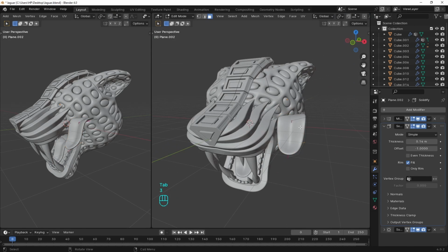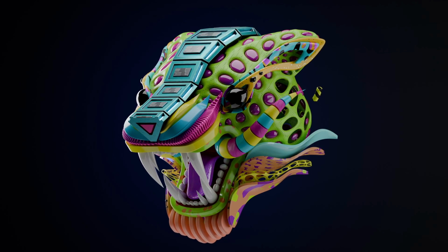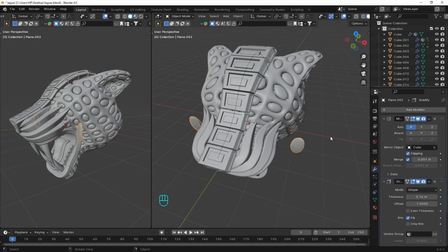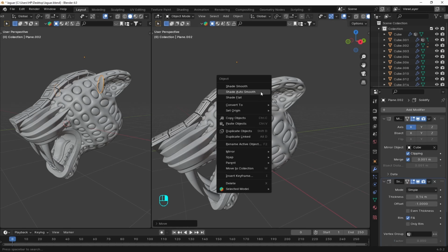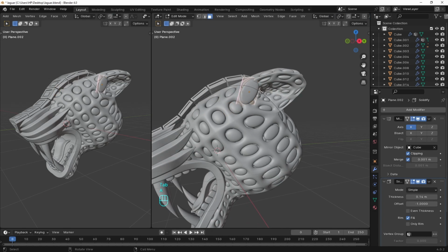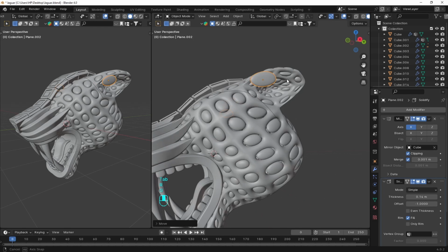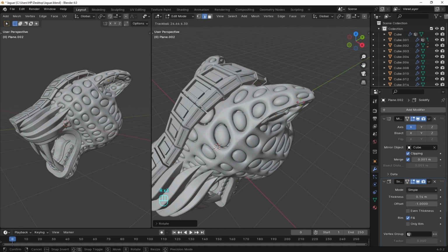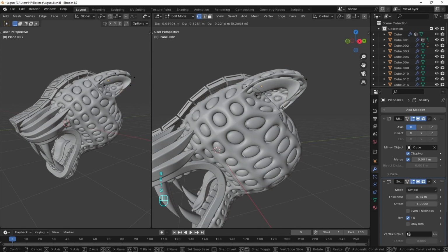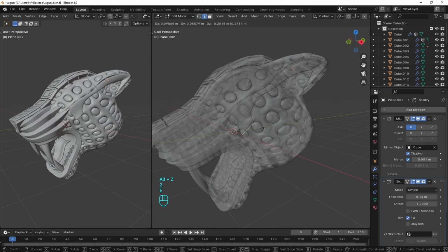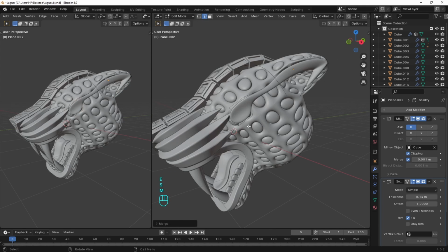Taking again a part of the mesh so we can build a few elements around the eyes. Just add the head as mirror object. We can also set back the origin point to geometry so it's easier to rotate, edit and all this stuff. Remove the edge creases if any, and like on the other parts you just extrude the edges in edit mode. Around the ears, down the eyes to model these elements. You can go wild or just follow what we are doing here.